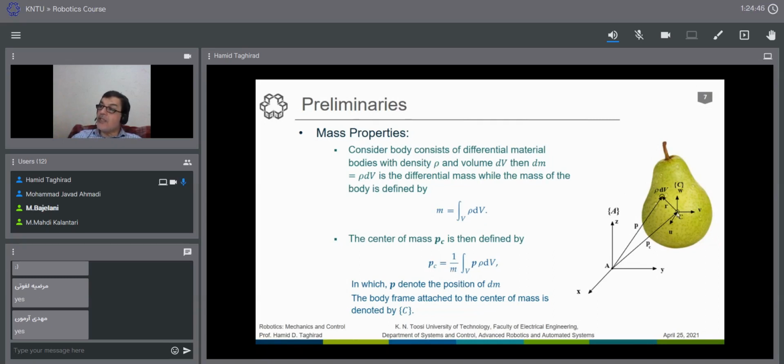the mass of the system times this center of mass gives the whole mass of the system times P. The position P times dm at each point, if you integrate it, gives you a position P times m. You know that the integral of rho dV over the volume is m. So m Pc is equal to the sum of mi pi.